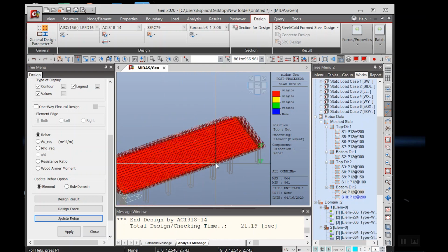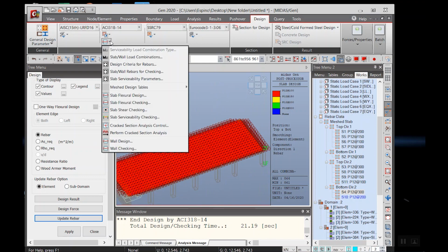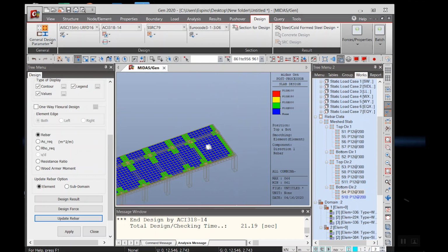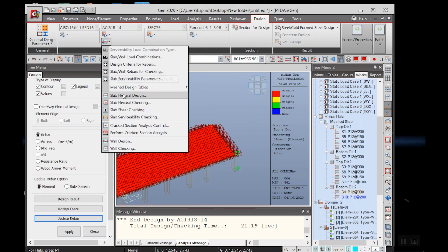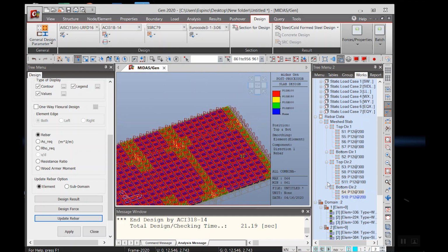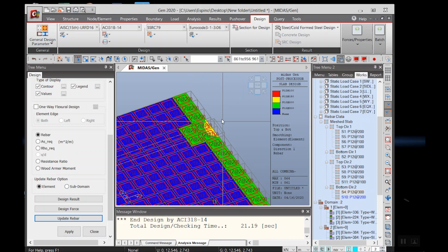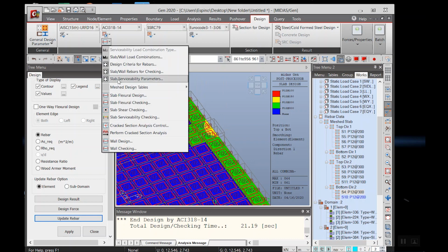After doing that, let us check the result. We can check if the changes that I have made will pass or fail. Since it is required that for this portion of the plate element we have to use the 200 mm spacing, I think there will be an issue if we check this portion of the plate. The issue I mean is actually a failure on the resistance ratio.